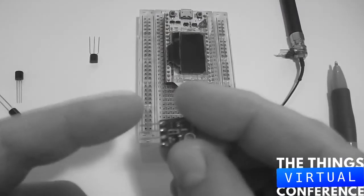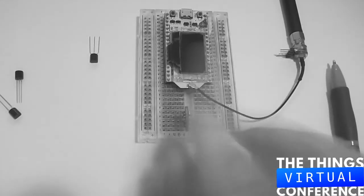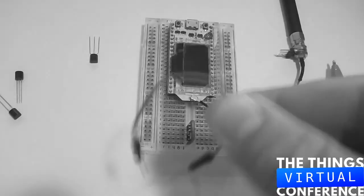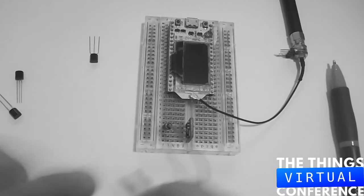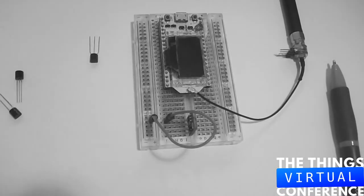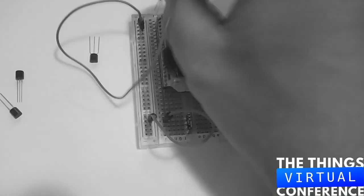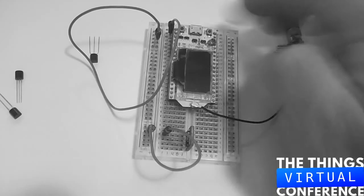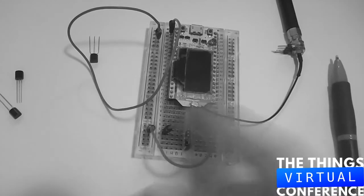So you would maybe take some sensor, and here are the pinouts. There's the supply of the sensor, there's a ground, and then there are two others for communication. You would put it in there. You would take something like these DuPont wires, or whatever they are called, and you would place maybe power here. Let's make the red one, no, it's black and white, but let's make the red one power. And you would take the power from the microcontroller here. Now, I don't know where the power is here, but let's just imagine it's the second one. So the power would run from the microcontroller, fed by the USB, over here to the right line of these two, down here into this one.